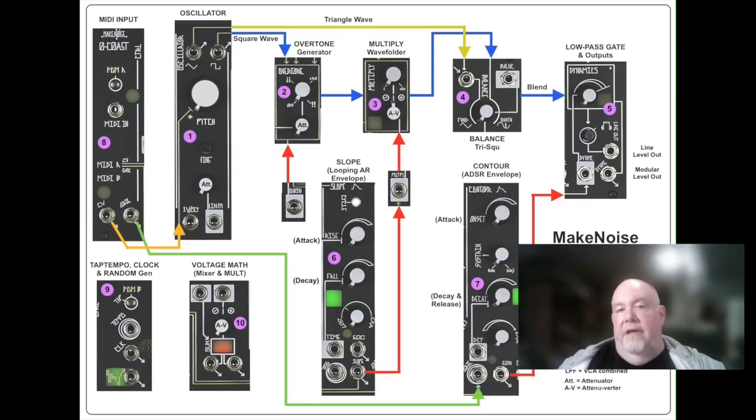There are 36 3.5 millimeter TS jacks that allow you to reconfigure the signal flow within the Ø-CØAST and interface it with other equipment such as a Eurorack format modular synthesizer. Now, 9 of the jacks have a white rectangular silkscreen background. That indicates that they are control voltage inputs. There's another one, the 1 volt per octave input of section 1, which is also a control voltage input.